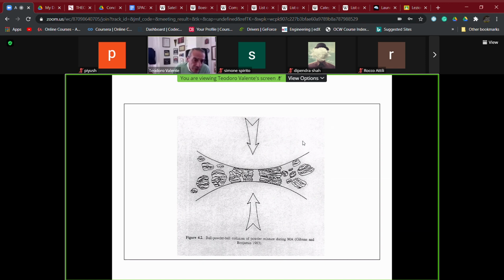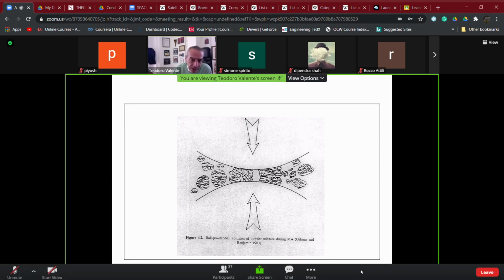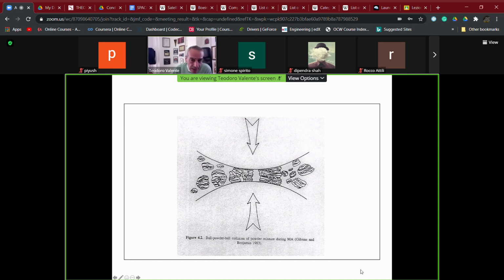But if we, as in our case, are thinking to use two different powders, for example, like in this picture, the white one and the black one, we can have a sort of layered structure inside the single powders, for which the thickness of the layer of material one, then another layer of the second material, then another layer, and so on, are going to be reduced by increasing the milling time.